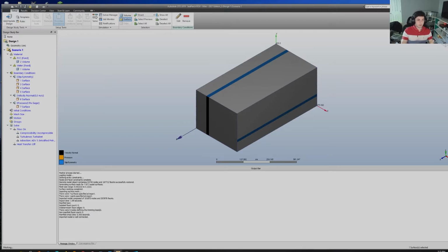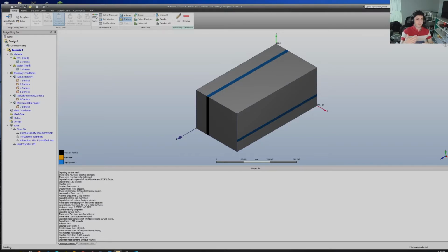After you create the surface mesh, which is creating the smaller triangles on the surface of the volume, the volume mesh is created by dividing the whole volume into smaller cells, which are then modified based on the surface mesh to create an accurate model that can be used to simulate the flow around the design.